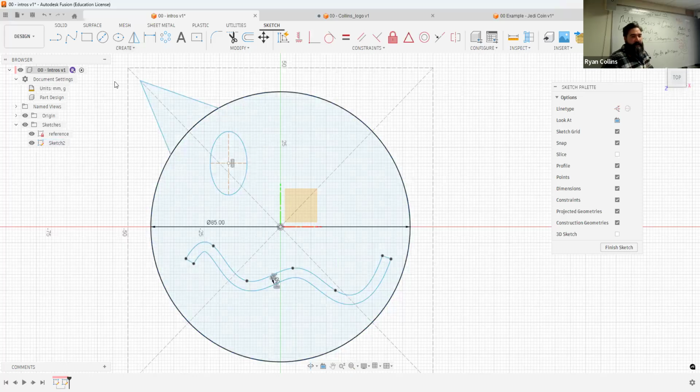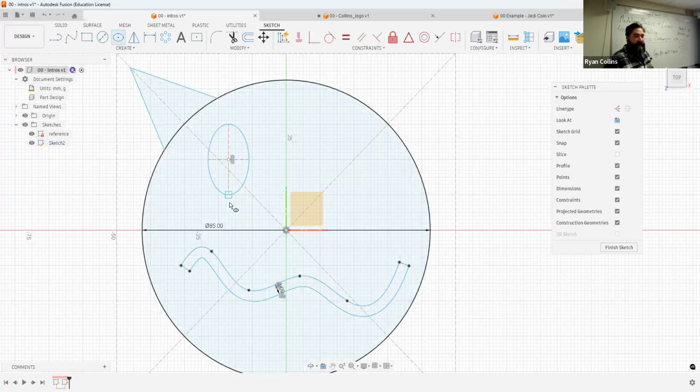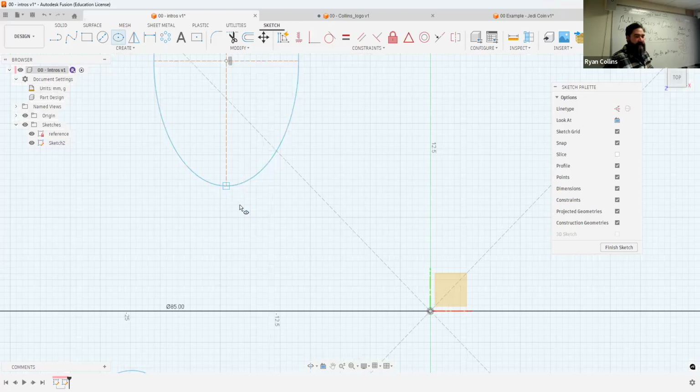All right. So from there, we could do some combining, maybe adding just a curvature up top. Like we talked about before, you can use pre-made tools or shapes and adjust those. So I just made this shape with an ellipse. Let's use another ellipse. I'm going to go down to the bottom. It doesn't even have to be at the very bottom, but you see my cursor changes. As I mouse around, the tool is a crosshair with a box around it, but as soon as I go across one of the lines, it changes to an X. That's because it's locking with that sketch and intersecting that.